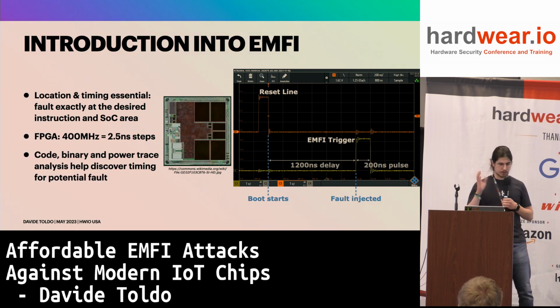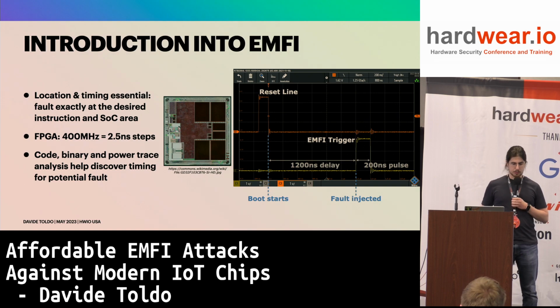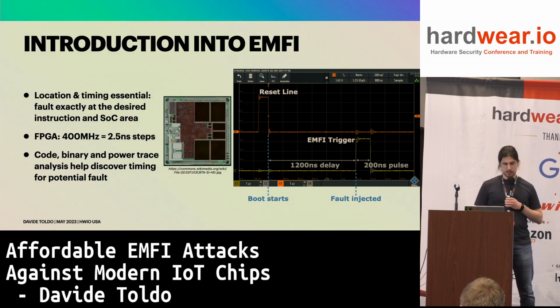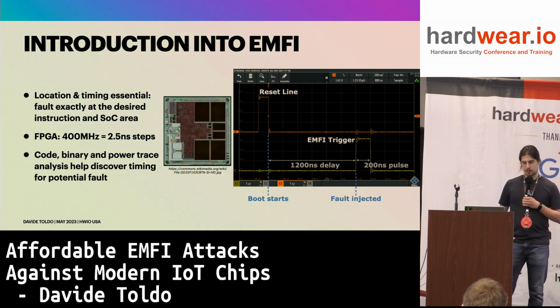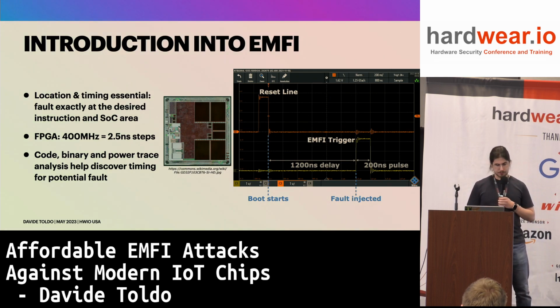Just so you have a picture about the time scale we're talking about, by using an FPGA for timing, we have 400 MHz clock, so it's a 2.5 nanosecond step size. This is fine for many targets, and if you're faster, you might need faster clock or more tries.